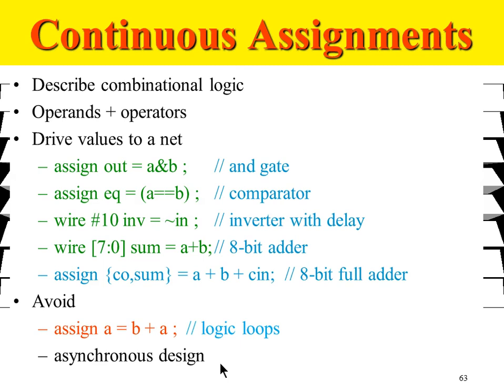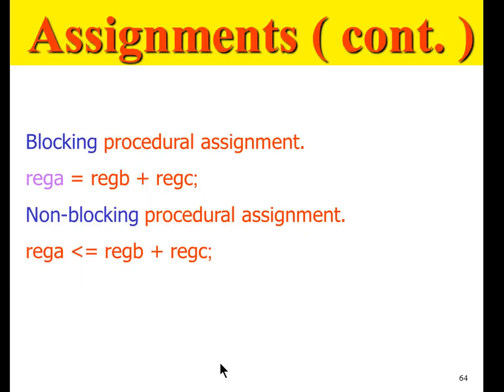No. Okay. The next concept is very important, called blocking assignment and non-blocking assignment. Blocking assignment is denoted this way: reg A equal to reg B plus reg C. The same thing is denoted as a non-blocking assignment when we say reg A angle equal to reg B plus reg C. This angle equal to is for non-blocking, just equal to will be for blocking.